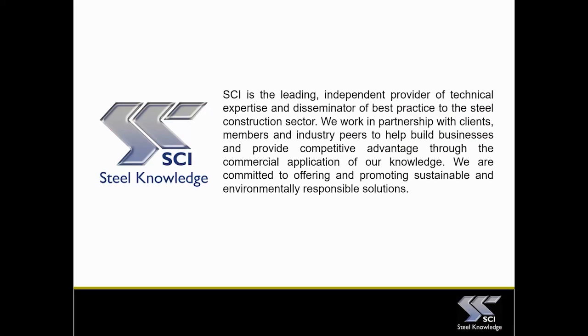So the first question is asking whether story-to-story module uses a pin connection. I think in most cases, module-to-module connections would be considered as a pin connection, yes. A question about whether you can interpolate between psi values. You can interpolate between the psi values, but also the expression is given, so you can calculate exact values as well.